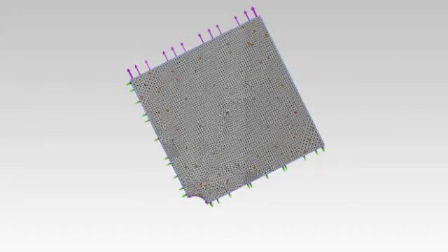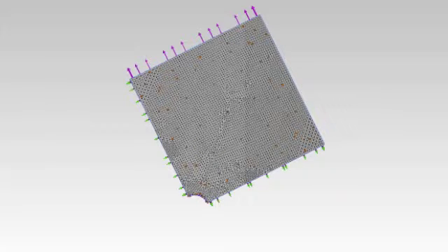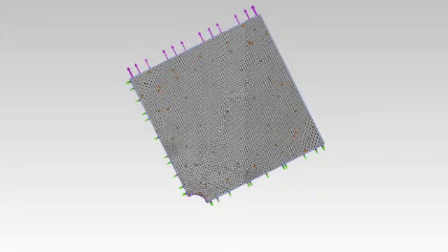Our study enabled us to reach the conclusion that stress around the circumference of the hole was much greater, which is shown by the fine nature of the mesh, whereas as you move further away from the hole, the stress concentrations decrease, which is shown by the coarse mesh.